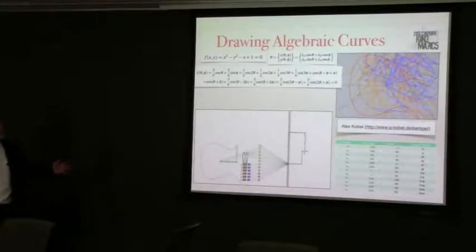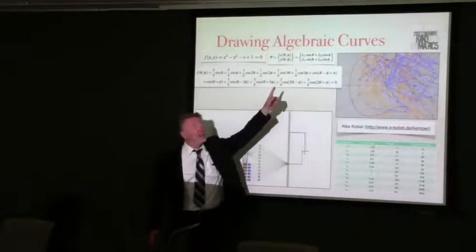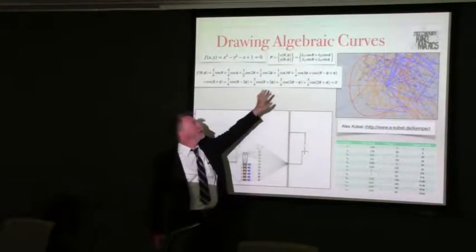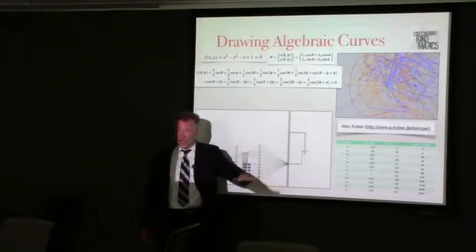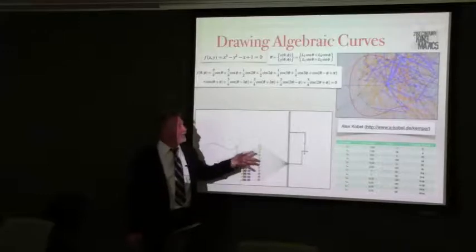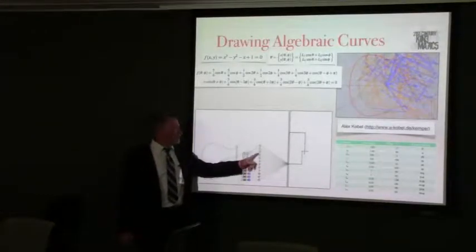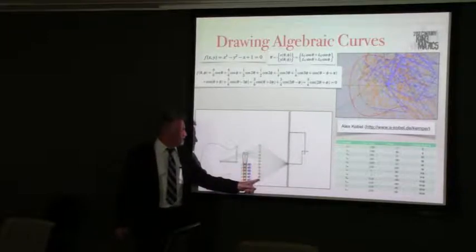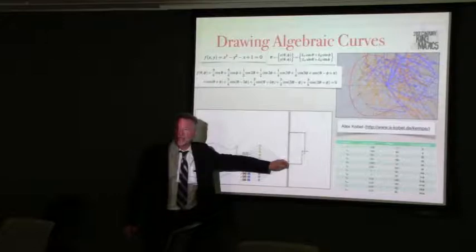Okay, so we go through the same calculation. We start with our serial chain, which is sitting up here. We transform the equations into projections on the x-axis. That's Kempe's trick. And now we introduce mechanical adders, and we use multipliers, and then we use pulleys just to move the data around.